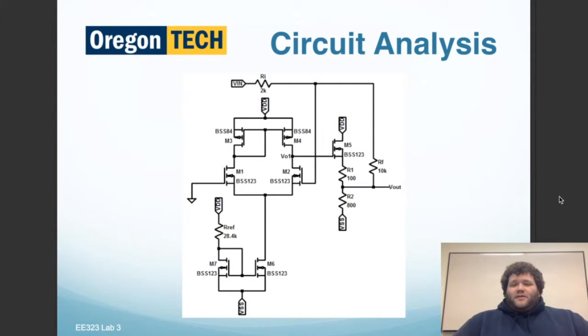Here is the diagram of our circuit that we used. As you can see here, here's the differential amplifier with the only MOSFET transistors. All transistors in this were only MOSFET. Here we have the inverting input, and it's connected to a negative feedback from the output. And the gain we're looking to get here is 5 based on the 2K and the 5K. And here's a current mirror, stage 1, stage 2.